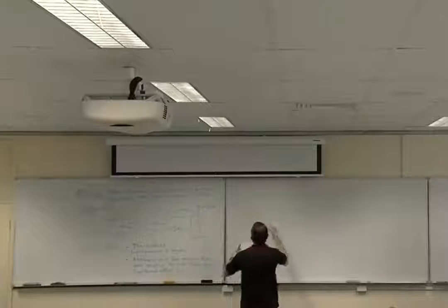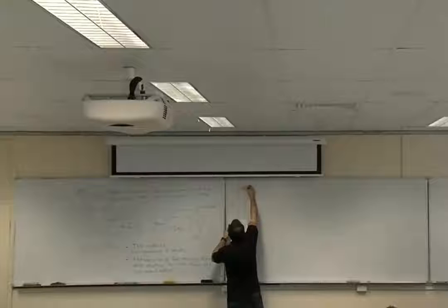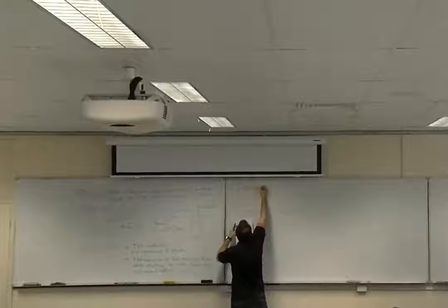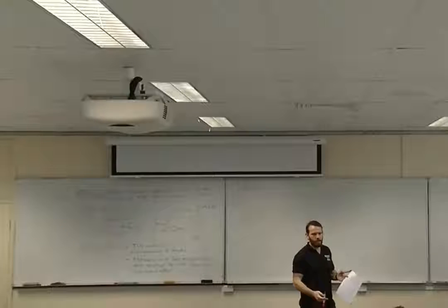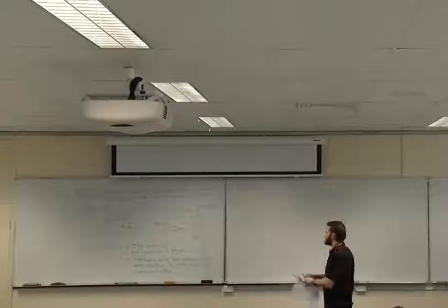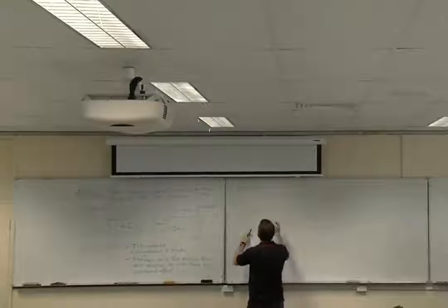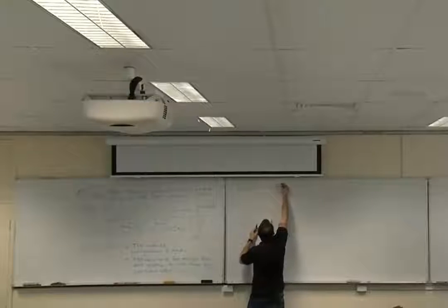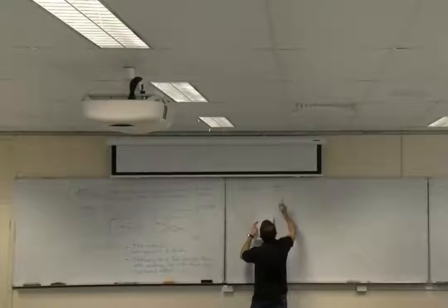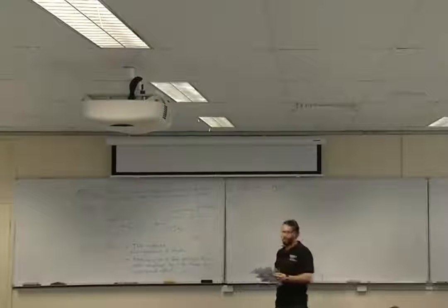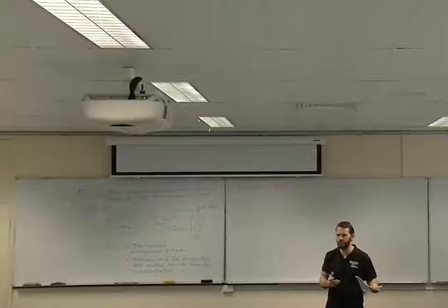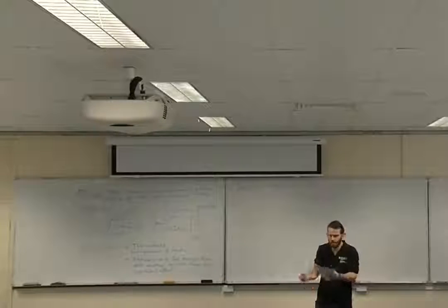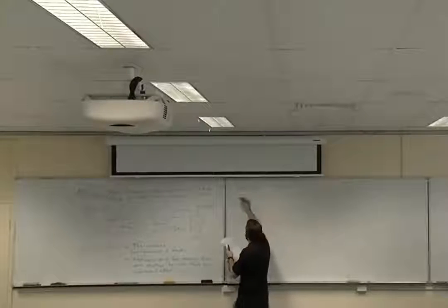So, analysis. Alright, so our assumption here is that they're separate, which means that we can analyse them completely separately. So I will analyse the hole first. First thing we do, you can either calculate the stress concentration factor or your nominal stress, it doesn't matter. Those are the two things you need to know. So let's say nominal stress.